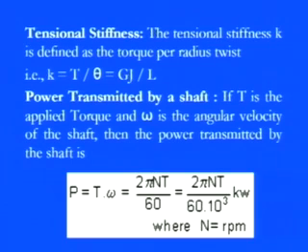So torsional stiffness, K, is equal to the applied torque divided by the twisting, meaning how much distortion there is. So whatever the angular twist is, K is equal to the applied torque T divided by the angular twist theta. Or once you put those things in, since T by J was equal to G theta by L, T by theta is equal to GJ by L.